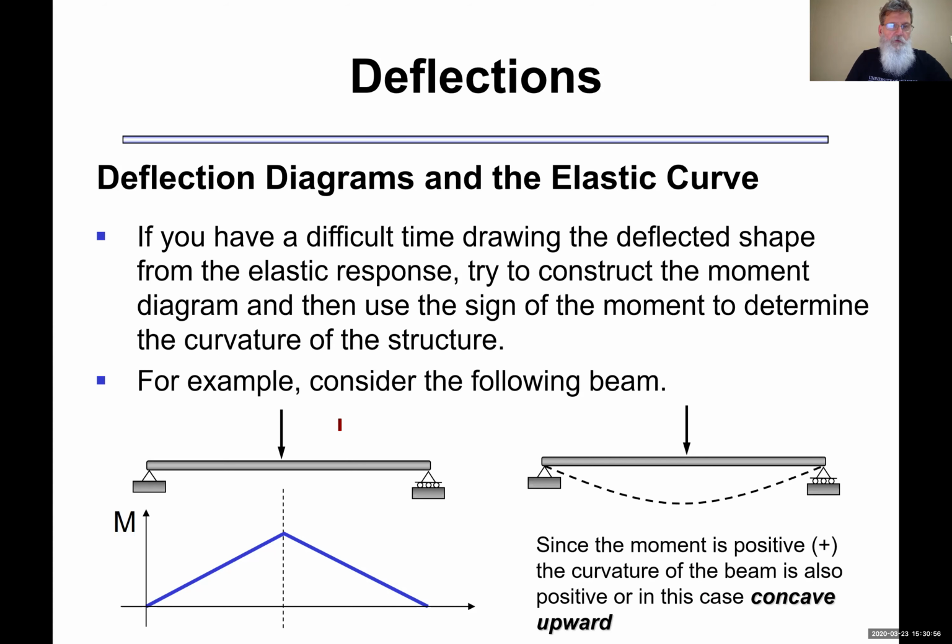So again, if you see the beam, draw the moment diagram, it'll give you an idea of what you think the displacement should be. You're making calculations on this beam and you say, hey, the displacement here is positive. Well, we know that's not true. Positive is up.